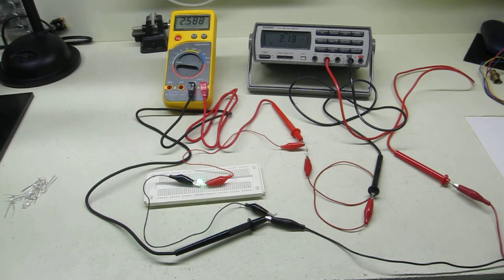The experiment itself is fairly simple. We start by varying the voltage across the entire circuit to get a current of approximately 1 milliamp. And if I vary this slightly, I get 1.06 milliamps on the meter. I then measure the voltage across the junction as 2.424.